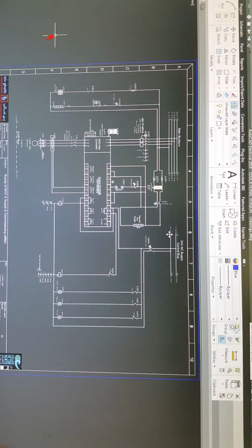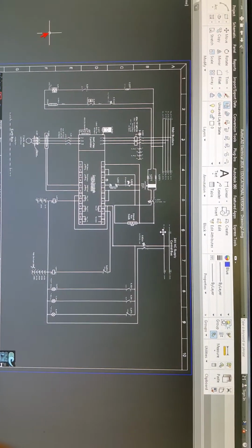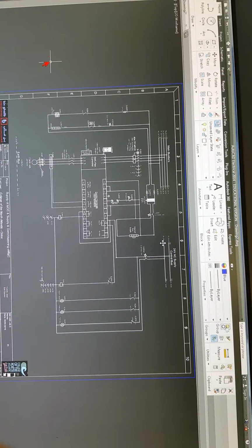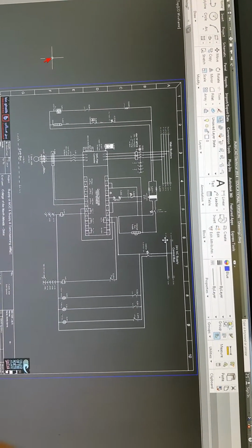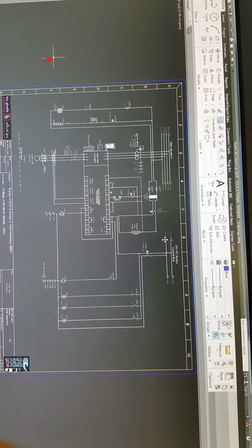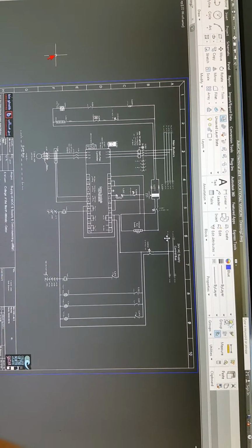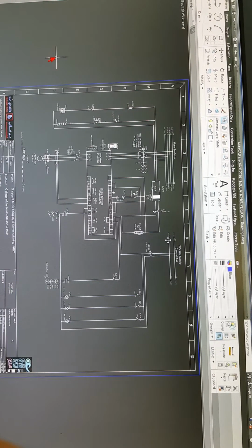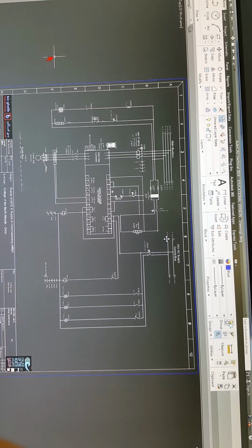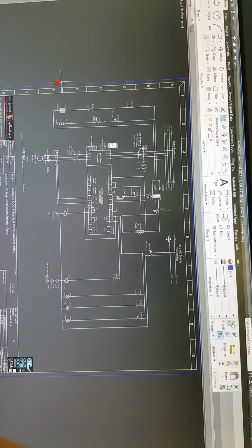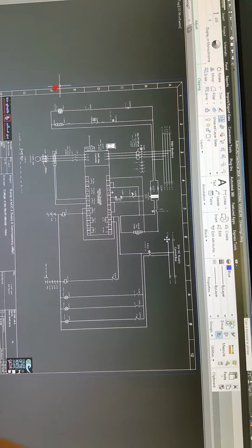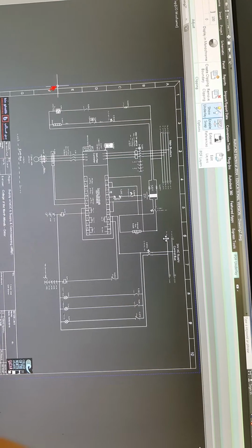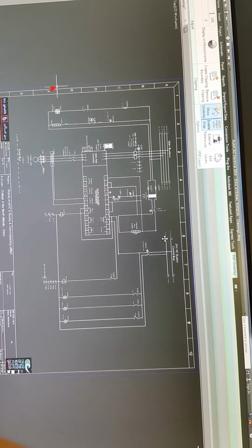Now, here's another idea that you might want to use. Maybe you want to put this image on a different layer. Why? So you can turn the layer on and off and see where you're progressing. Actually, this idea came from one of my students. As I'm tracing, I could delete this and then press Control Z and bring it back.